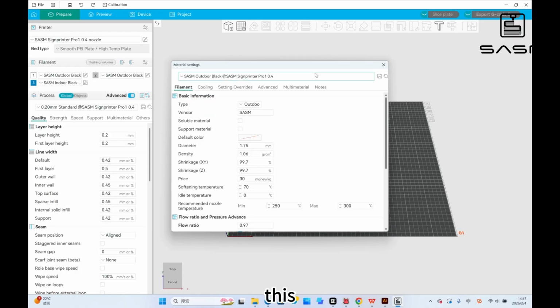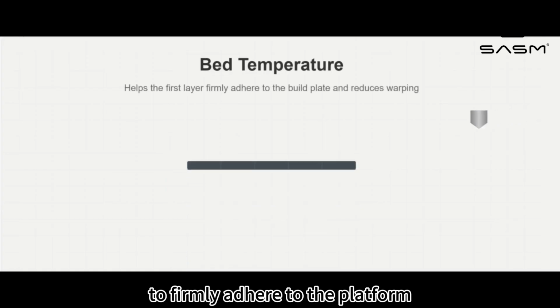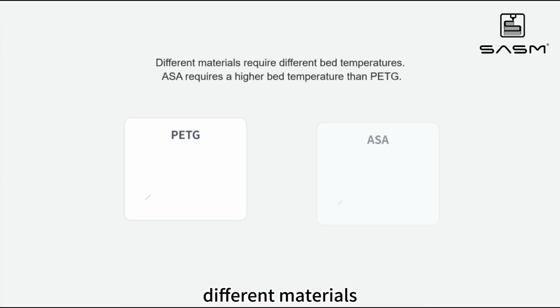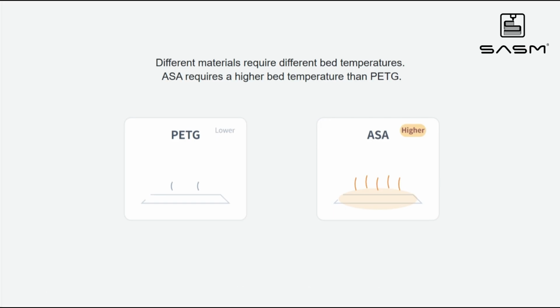Heated bed temperature. This is the temperature of the heated printing platform. Its main purpose is to allow the first layer to firmly adhere to the platform and prevent the corners from warping. Different materials also require different bed temperatures, and ASA requires a higher bed temperature than PETG.